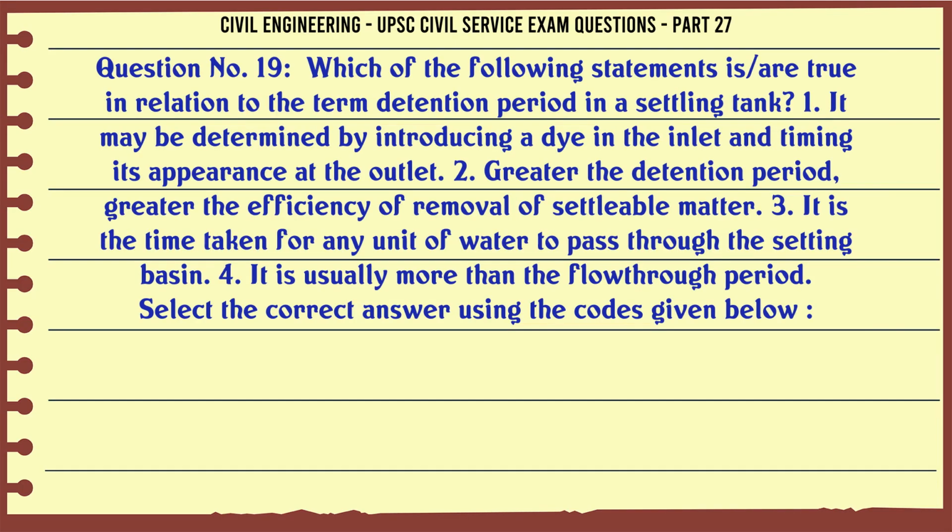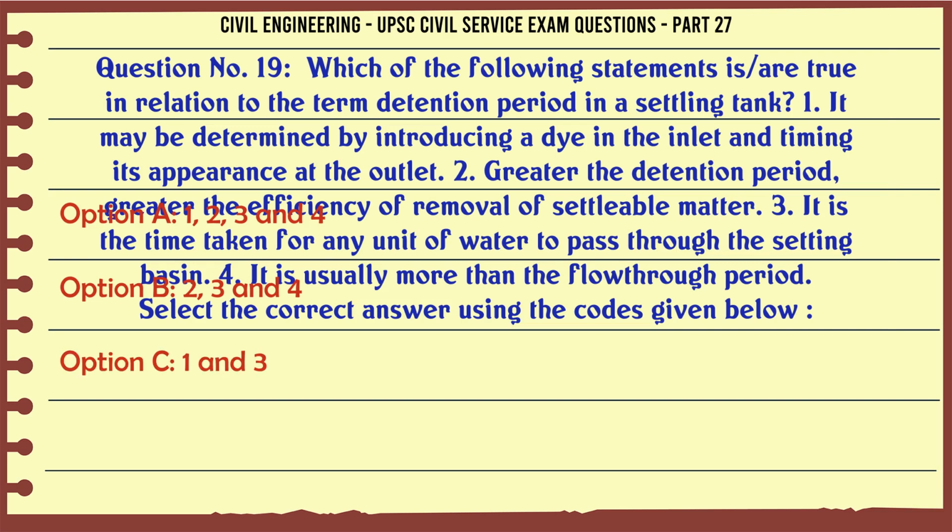Which of the following statements are true in relation to the term detention period in a settling tank? 1. It may be determined by introducing a dye in the inlet and timing its appearance at the outlet. 2. Greater the detention period, greater the efficiency of removal of settleable matter. 3. It is the time taken for any unit of water to pass through the settling basin. 4. It is usually more than the flow-through period.